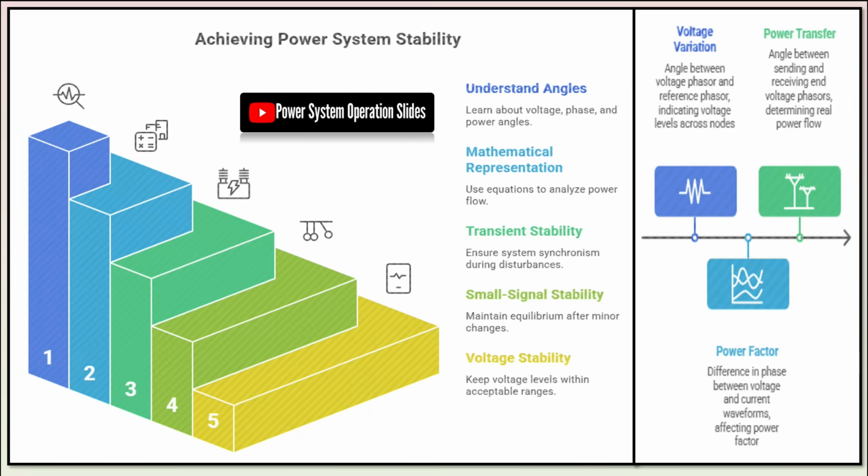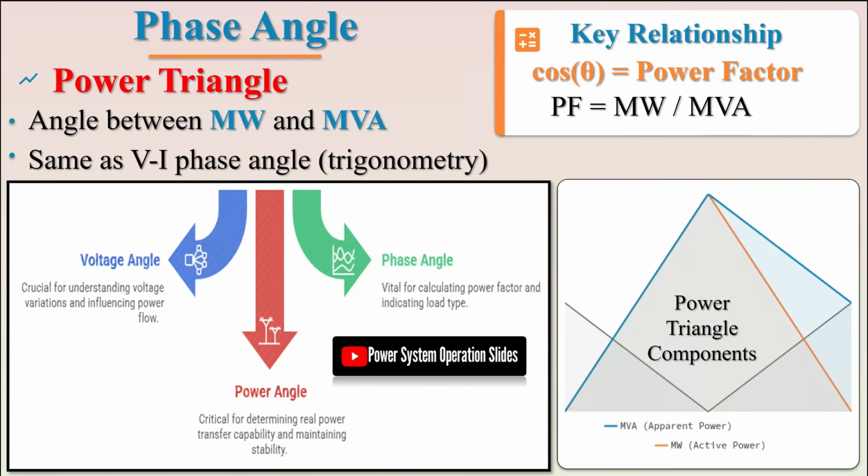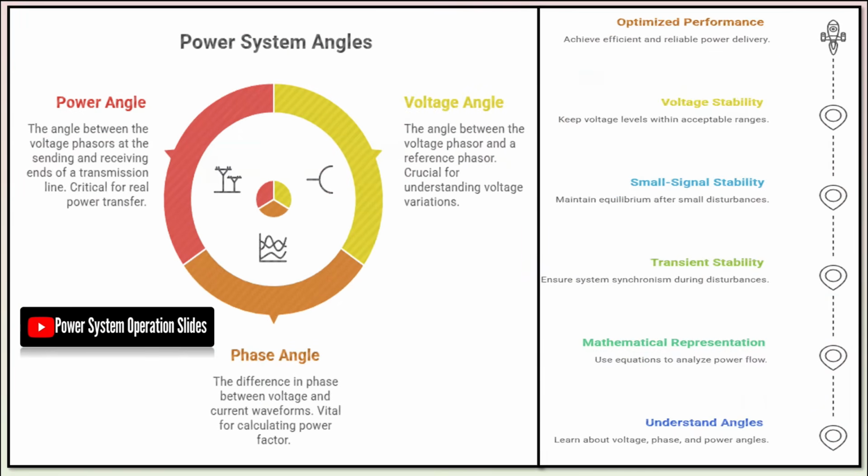Unlike the phase angle, which is measured at a single point, the torque angle is an internal parameter that describes the magnetic interaction within a rotating machine, ignoring secondary effects such as resistance voltage drops or armature leakage flux to focus on the core magnetic phenomena. In a generator, the rotor spins at synchronous speed, driven by a turbine, and its magnetic field effectively drags the stator's magnetic field along, inducing voltage in the stator windings. However, the stator field cannot quite keep up with the rotor field, resulting in a slight lag. This angular lag between the rotor field and the stator field is precisely the load angle.